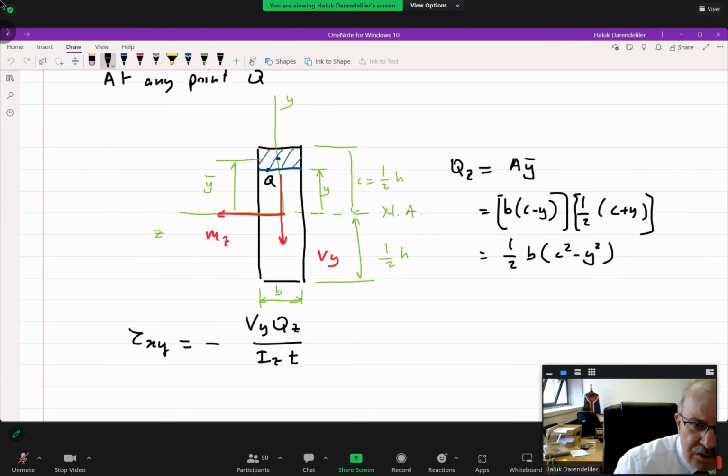I'm going to say one more thing, although I'm going to raise it later. If you calculate the Q of this area, look here please. If you calculate the Q of the remaining area, you end up with the same magnitude but opposite sign, because when you add them, they must sum to 0. So you can use both. This is the centroid of that area. Do you have any questions so far? Because what follows is very straightforward.